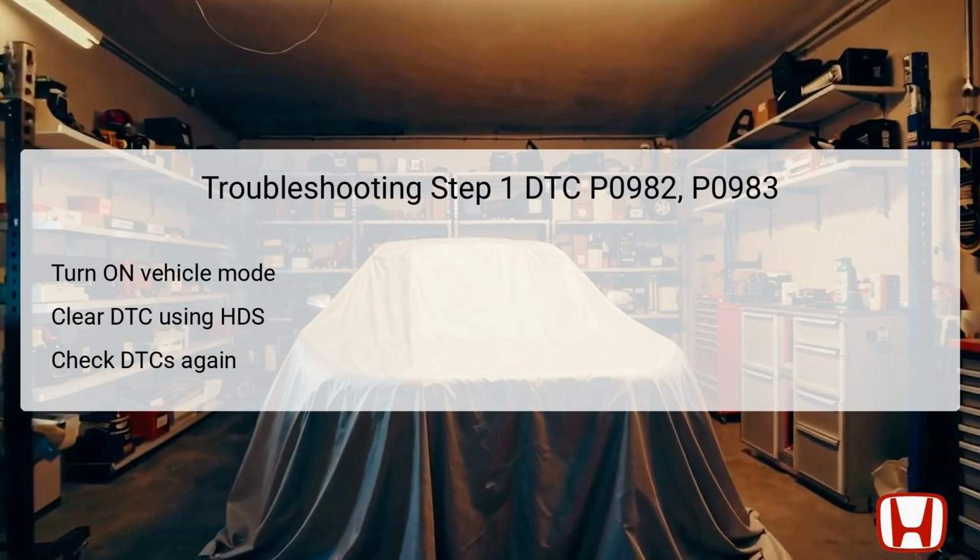After several seconds, check the HDS again for any pending or confirmed DTCs. If either P0982 or P0983 is still indicated, it confirms that the issue is persistent and that further troubleshooting steps are necessary.